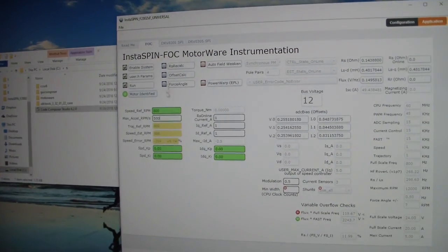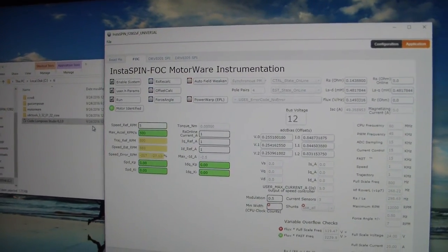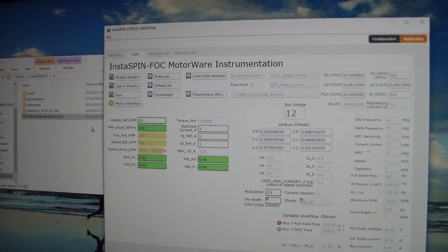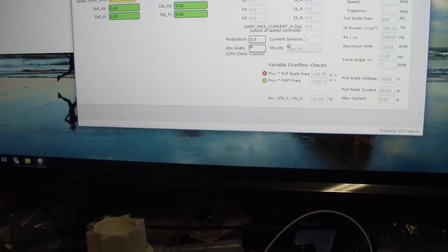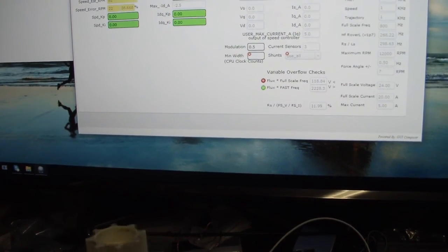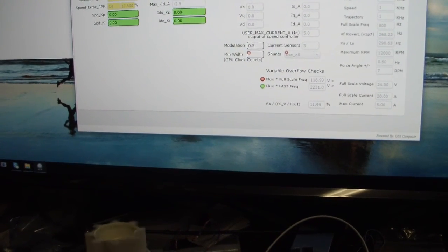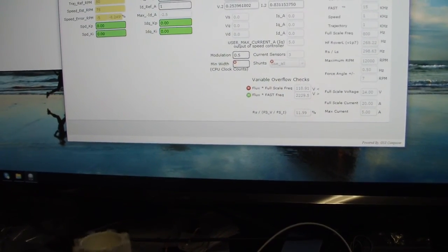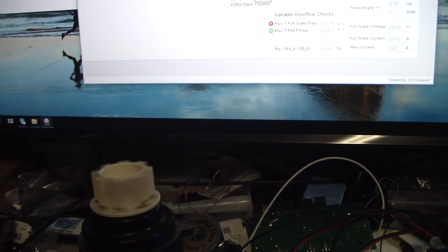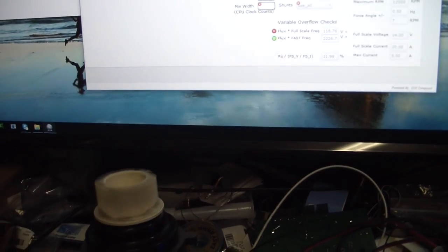And if you go to a lower RPM, let's say 50, of course this is not enough, so the motor will not spin smooth because it has to stop in order to get to this low RPM. Let's try to see what is the acceptable speed that will make it run more or less smooth. So I think this is something about 100 RPM, maybe 150. Yes, 150, it is very smooth. Okay, that's all for now.